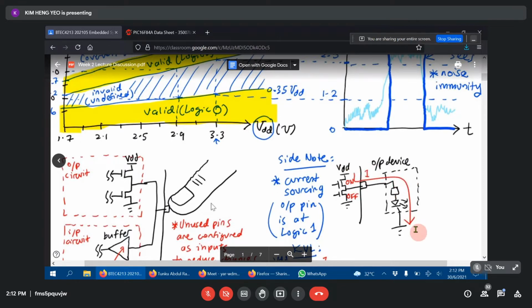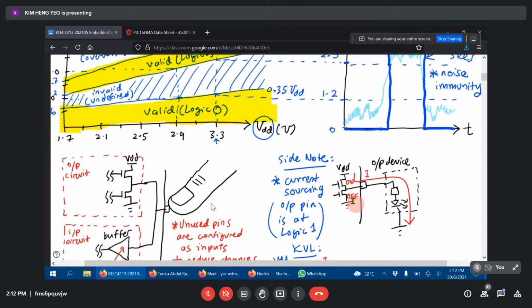Now your microcontroller has a power supply pin, a VDD VSS power supply pin. So that's where the power comes from. Internally, this is a very simplified drawing of the power supply circuit, your GPIO peripheral inside of our controller. If you want to supply a logic 1 at this IO pin, then internally the upper transistor turns on, and the IO pin will be connected to VDD internally, so